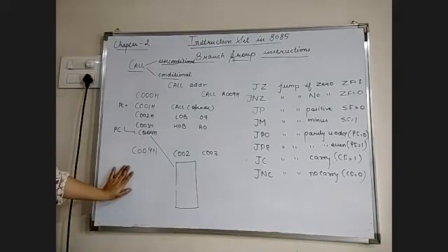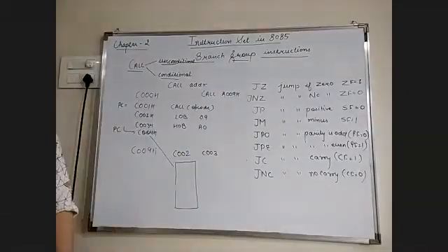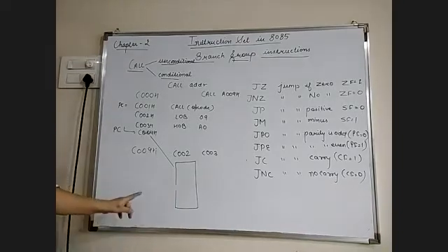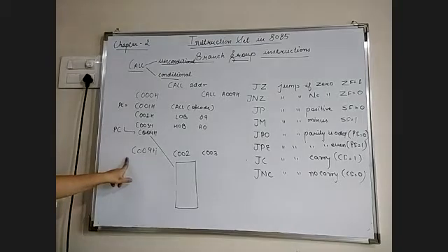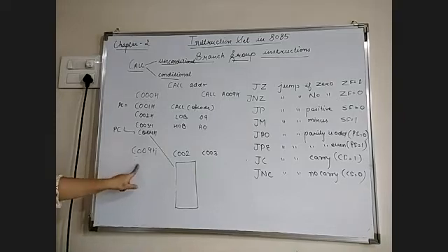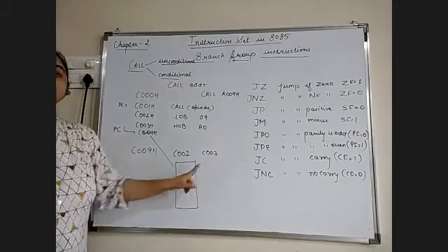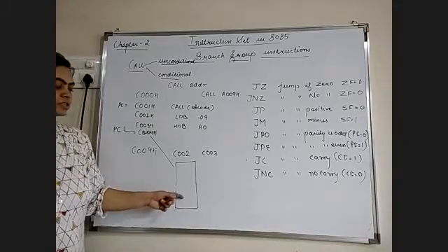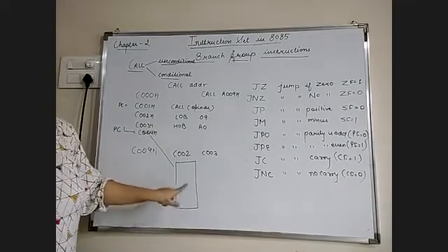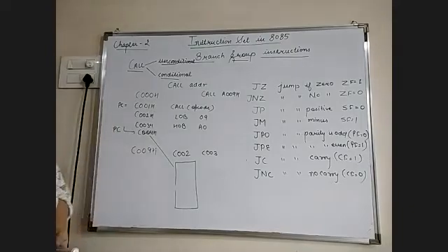Okay, so once the execution of the subroutine program is done, it is essential to transfer the program control back to the main program. So how can the microprocessor come back to the main program? By checking the contents of the program counter in the stack memory. The microprocessor checks the contents of the program counter here, and after popping the contents from this stack memory, it will get back to the main program. Okay, so this is how the call instruction will work.